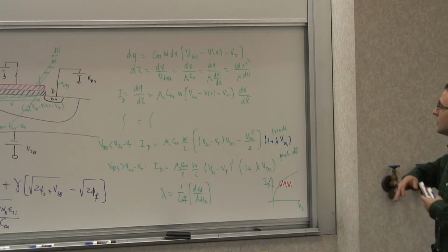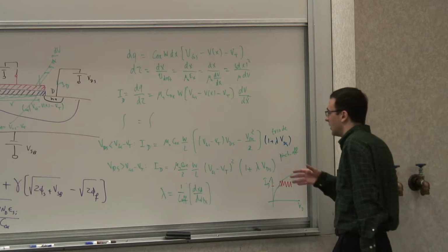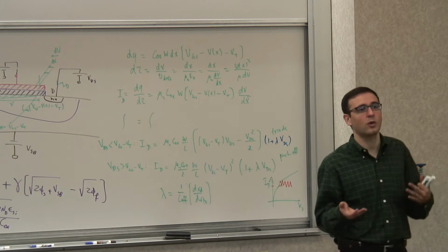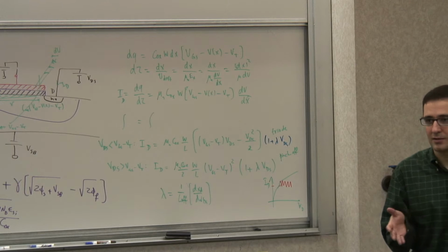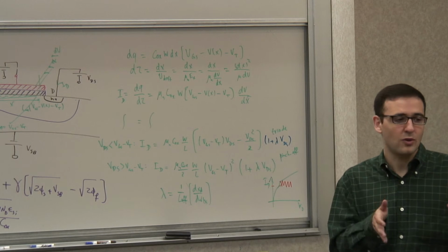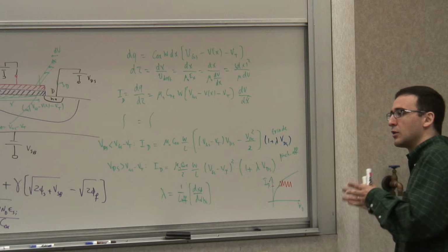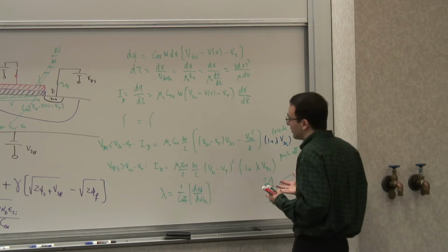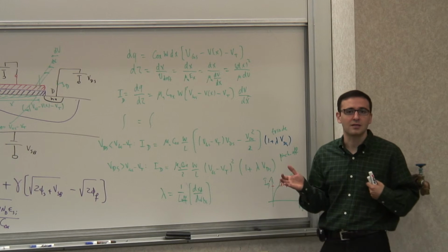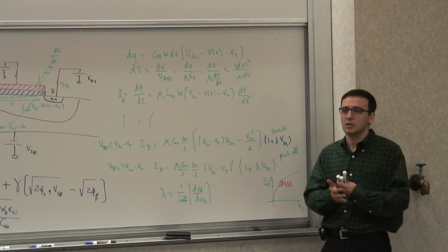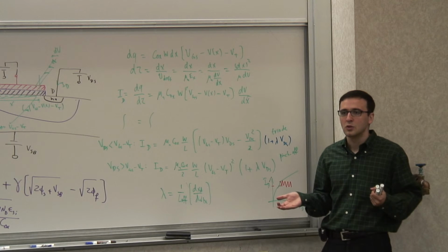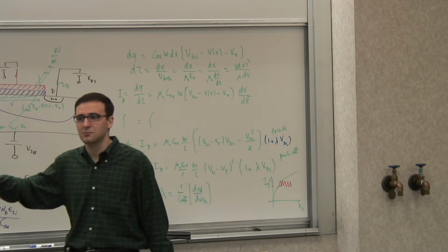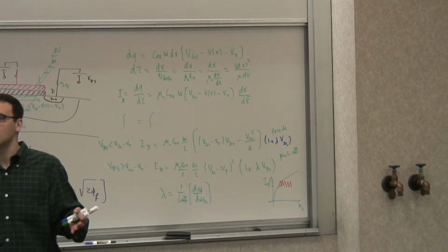But for simulators, there are more sophisticated models like BC models and then other kinds of models that have been developed that capture a lot of second order and third order effects, which is what you really care about when you're using a simulator. In a sense that you want it to give you as accurate a result, as close to reality as possible. But for your hand calculations, you never want to use all those things unless they are really first order effects in a certain case, because it becomes completely intractable. You will see even with these simplified models, many times we'll linearize them, and even with a linearized model, we will have a lot of work to do in hand calculation.